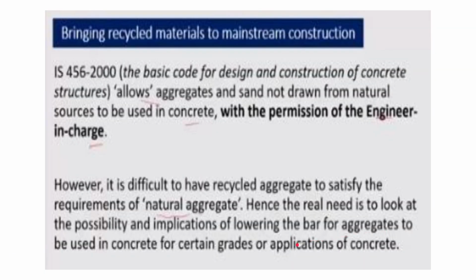Okay. So after going through all of this, you may have a question in mind: can we bring recycled materials to mainstream construction? So the answer is definitely yes. As per IS 456 2000, which is the basic code for design and construction of concrete structures, it allows aggregates and sand not drawn from natural sources to be used in concrete, but it has to be done with the permission of the engineer in charge. But one factor which has to be kept in mind is that the recycled aggregate needs to satisfy the natural aggregate requirements, which is not possible.